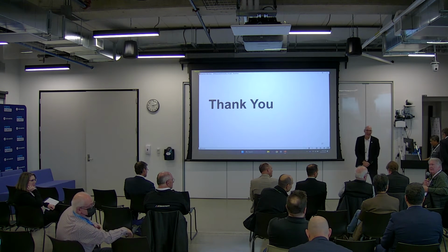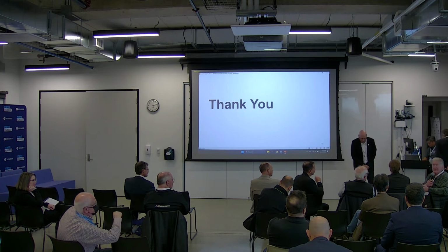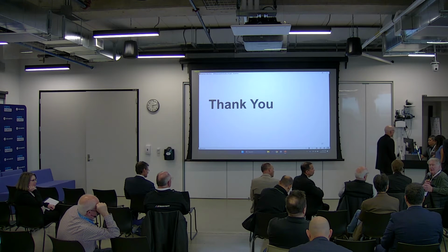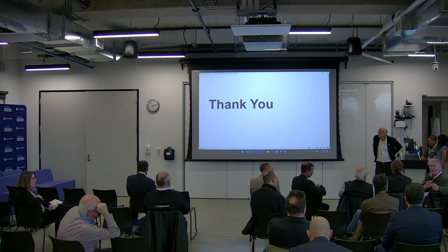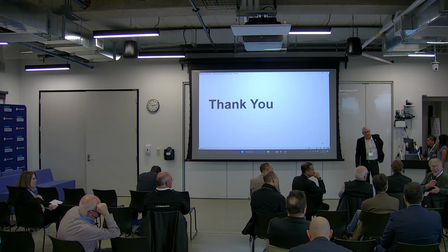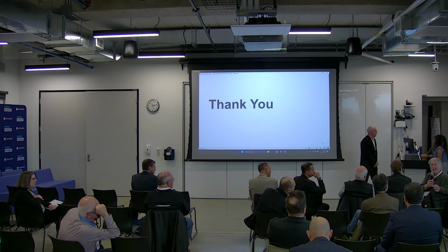In the time distribution world where you're dealing with standards, whether it's IEEE, whether it's IEC, whether it's ATSC, whatever it is, if there is a time boundary in there, it's got to be traceable to something. And traceable means that you have a methodology of tracking the source of that timing back to what's called universally coordinated time, which comes from the International Weights and Measures of BIPM in France. So in most of the very high-end timing systems, one of the functions is traceability.